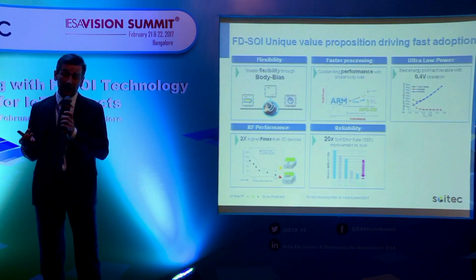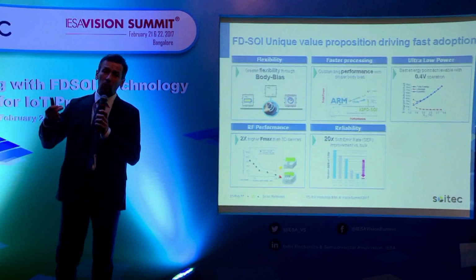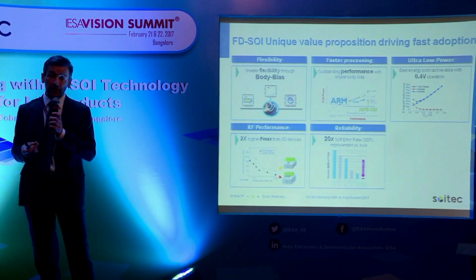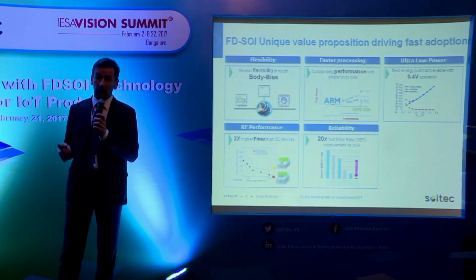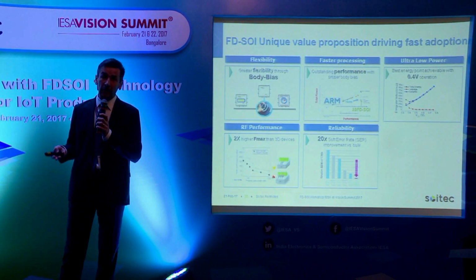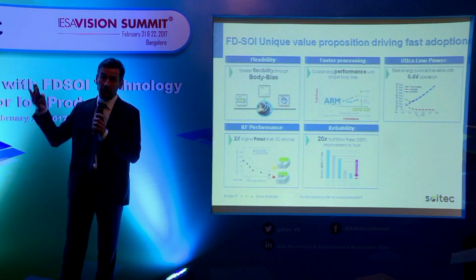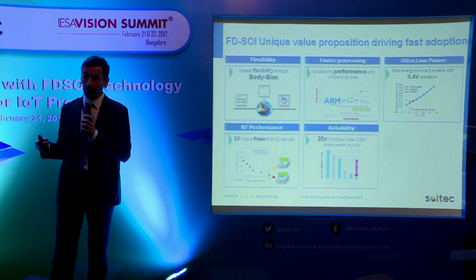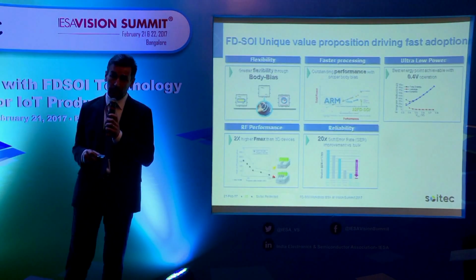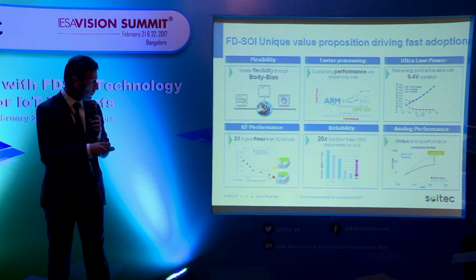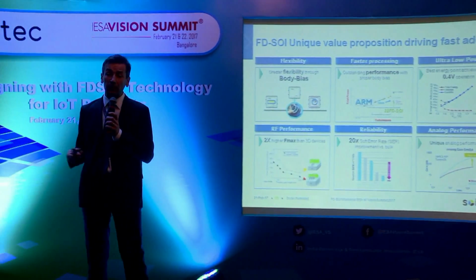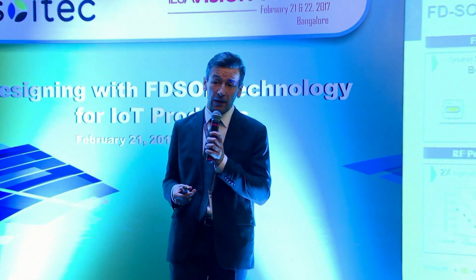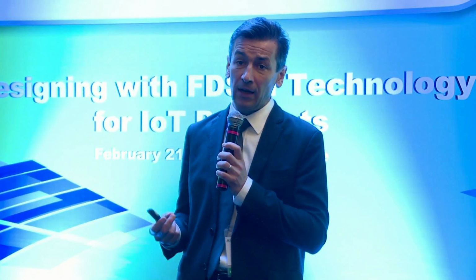Reliability. This is again a core value of SOI in general, but even more amplified on FDSOI, the fully depleted type of substrate, where soft error is significantly lower than bulk or any 3D structure. For many applications in the past, it could be military or satellites, but now in the automotive industry, this type of feature is becoming a huge differentiator in chip design. And finally, there are RF performance limits and analog performance, also much better on FDSOI than any other technology. So you see here this picture, just a big snapshot of what FDSOI can bring as differentiation to your design, at device level or at system level.